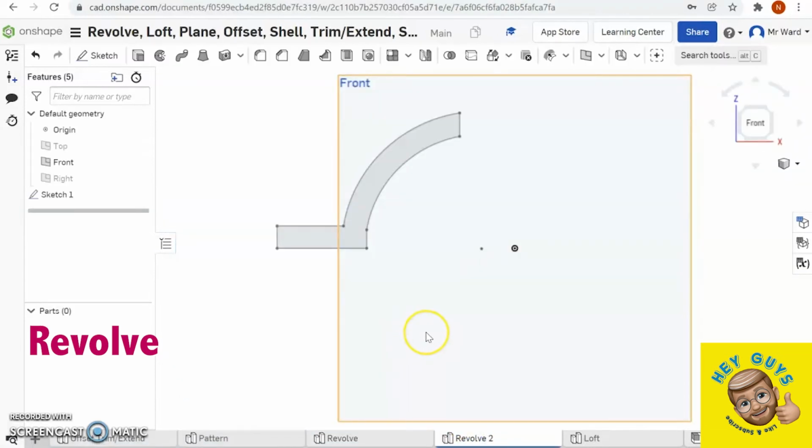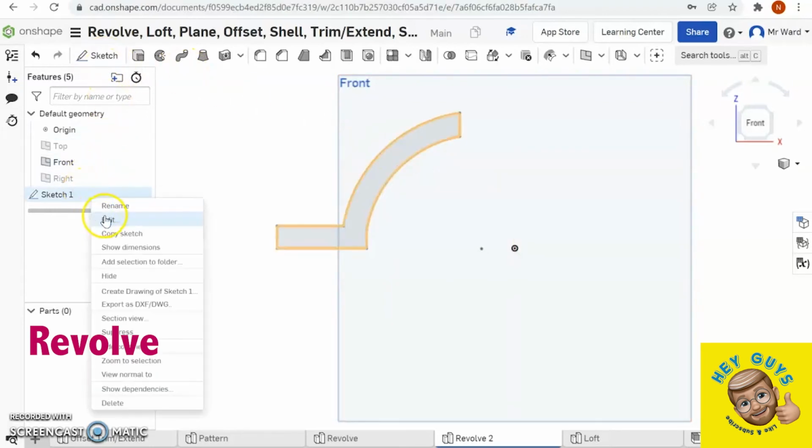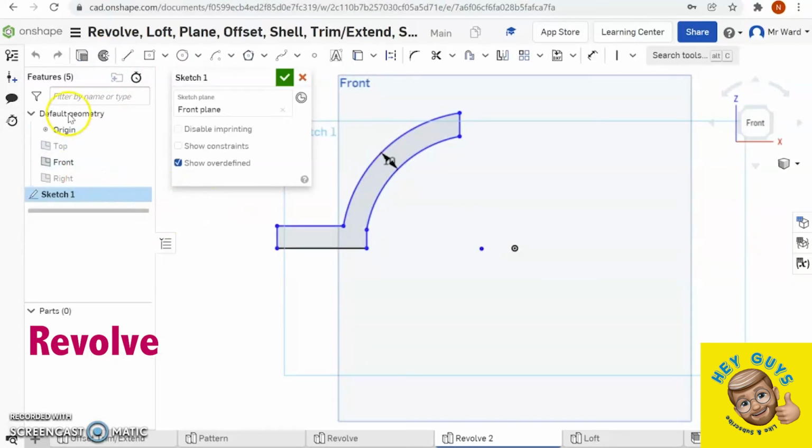So another way we could use Revolve is that it doesn't have to be a line that's necessarily a part of it. I can actually create another line. So I'm going to go back to Sketch, edit this sketch, and add in a line, but this time it's going to be a construction line. So it doesn't really exist as a line in space that's going to occupy something.